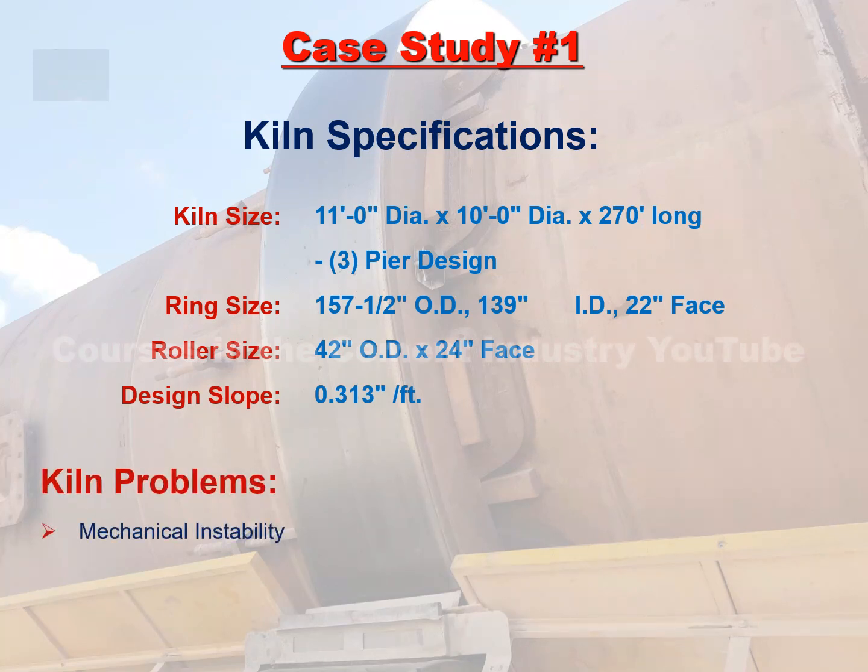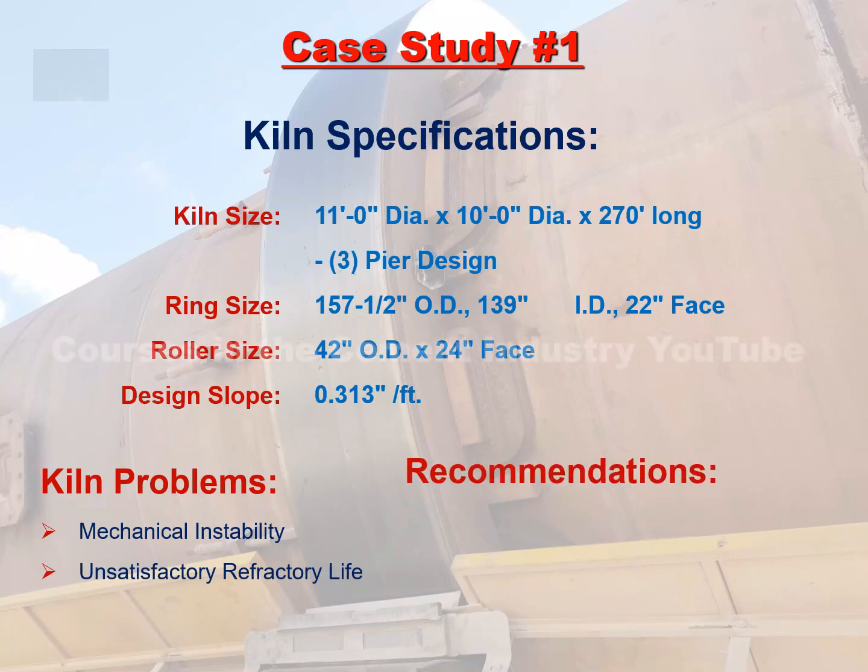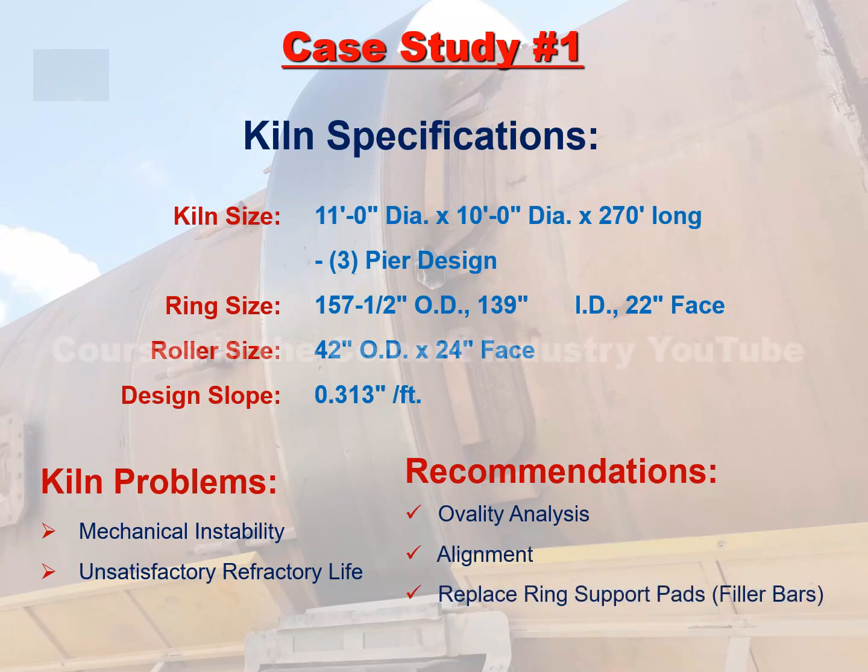Mechanical instability. 2. Unsatisfactory refractory life. Recommendations. 1. Ovality analysis. 2. Alignment. 3. Replace ring support pads, filler bars. 4. Recondition rings, and adjust rollers.